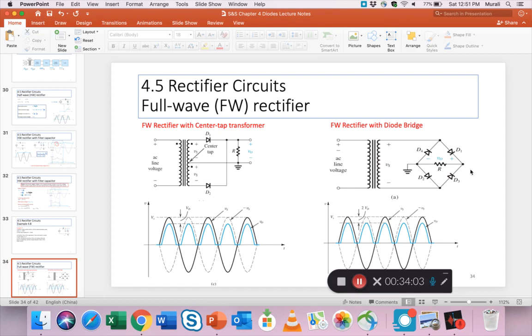I think you saw the 2 LEDs light up in pairs. So you're familiar with it, but if you want to trace what happens when this line is positive, D1 conducts and D2 conducts. The current flows through D1, through the load, out of D2 and then back. And the opposite happens when this is positive. When the lower terminal is positive, D3 conducts, the current goes through R, then D4 conducts and it comes out. Okay, so that's the simplest way to understand it.